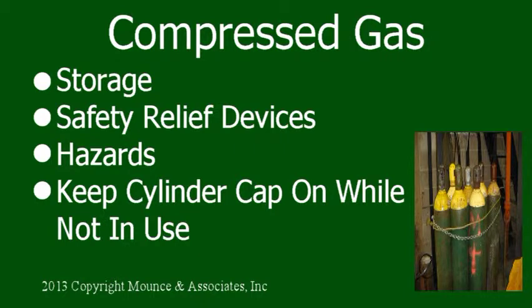Compressed gas. Compressed gas has many hazards such as asphyxiation, poisoning, projectile, fire, and anesthetic effects. It is important to know which flammable gas you are working with. Flammable compressed gas must be 20 feet or more away from combustible compressed gas, for example oxygen, or separated by a 5-foot wall with at least a 1/2 hour rated wall.